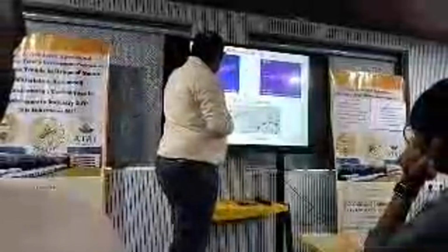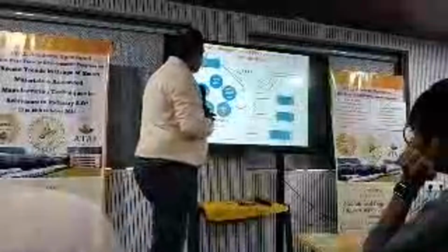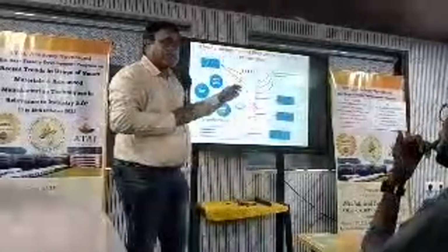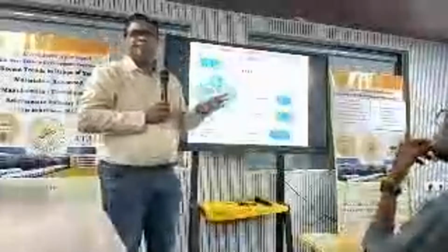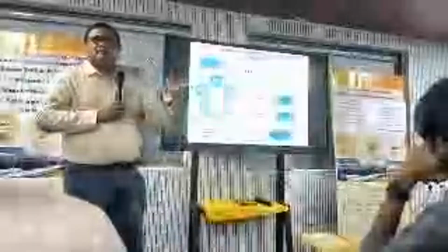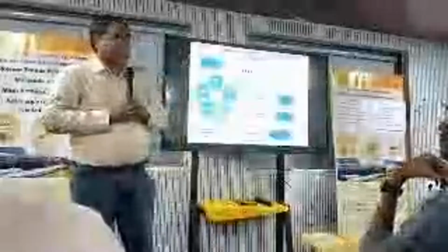And this is one of the ship's temperature points. This is the comparison measured versus predicted. And the exhaust, we have seen the gas turbine exhaust, both temperature is high, sound also more. So that's why the thermoacoustic silencer, the name is, it will reduce the temperature of the exhaust gases as well as the sound energy of the exhaust gases. It is a combination. By using single equipment, we can reduce both noise as well as the temperature.